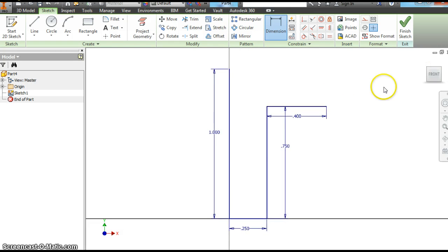Okay. And now we're going to connect this with an arc. So I want you to do a 3-point arc. Click here and see how it turns green. Okay, then click here, should turn green, and now you can kind of control that arc there. Let's do that.